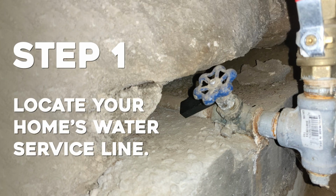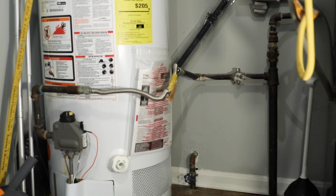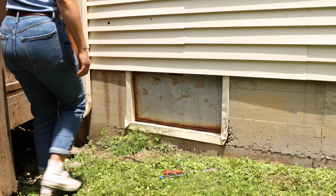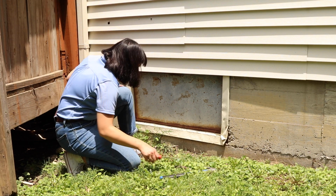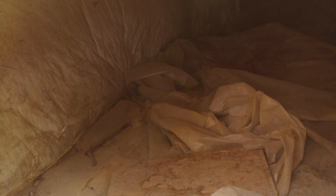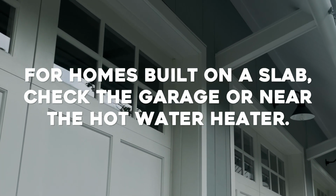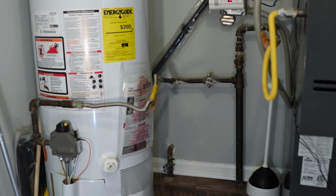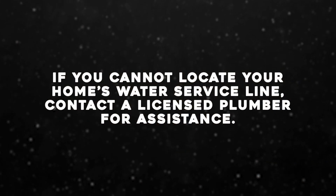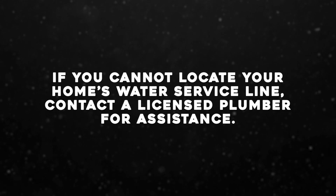The first step is to find the water service line in your home. This will be a pipe entering your home where it connects with the water shutoff valve. If your home has a basement or crawl space, check there first. Typically, water service lines enter the home at the lowest level of the structure. For homes built on a slab, check in the garage or near your water heater. The incoming water line usually comes through the foundation near the front side of your house. If you cannot locate your home's water service line, you may contact a licensed plumber for assistance.